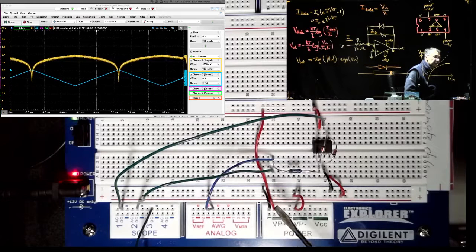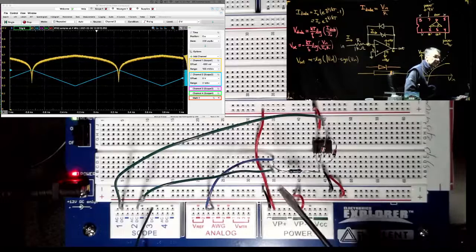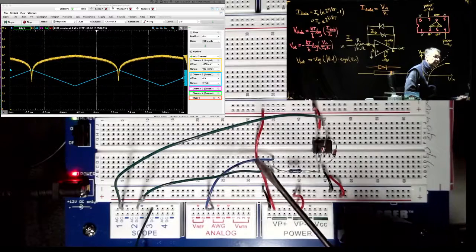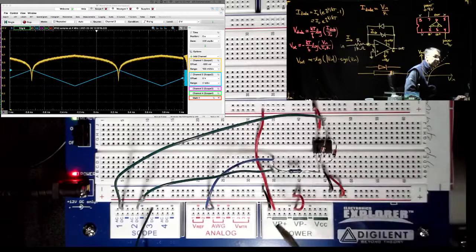And then it's a little awkward, but this long red wire is where the positive voltage is distributed from the power supply up to that top red bus. And then I'm using this little thing with the minus sign, which is a ground. So this black wire is basically distributing ground to the blue power bar on the bottom. And then scope channel 3 I'm not using for this exercise.